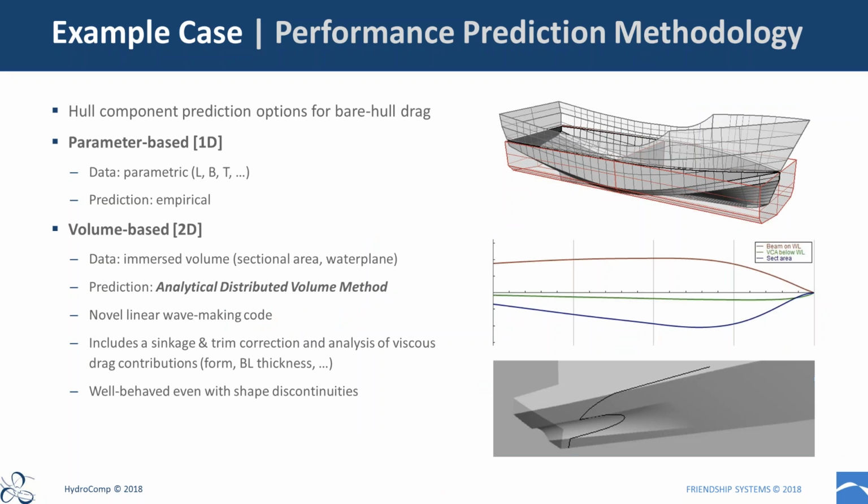What we're really interested, again, is the hole in the water. And for hulls like the one that we were using in the case study, a round bilge transom stern, traditionally falling in that semi-displacement regime, the midship position becomes largely irrelevant hydrodynamically. So the alternative to that is to use maximum section area, which in the case of the blue line here, the sectional area curve, we can see and identify what the maximum section area is going to be.